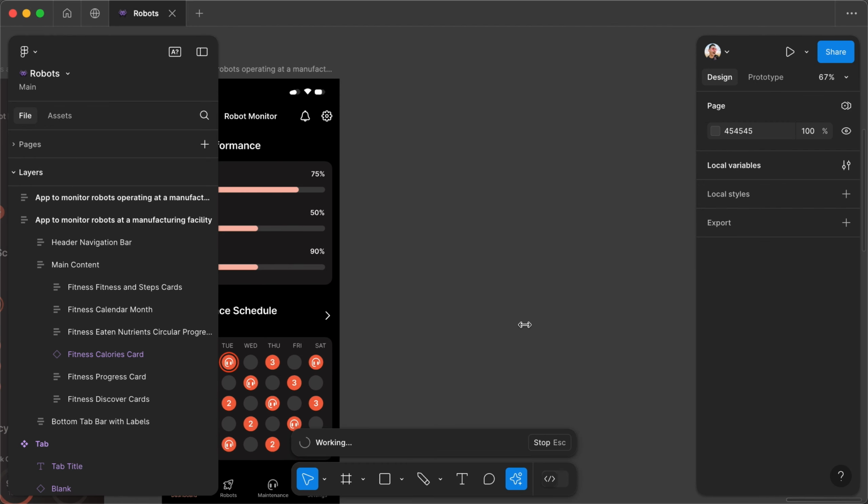For the final example, I'd like to show you something a bit more complicated. How do we turn these items with icons into a new component? It's not possible to do it in one click, as you can see in this similar example. The icons would get reset since they are not component instances and can't be swapped. Start with converting icons into individual components.